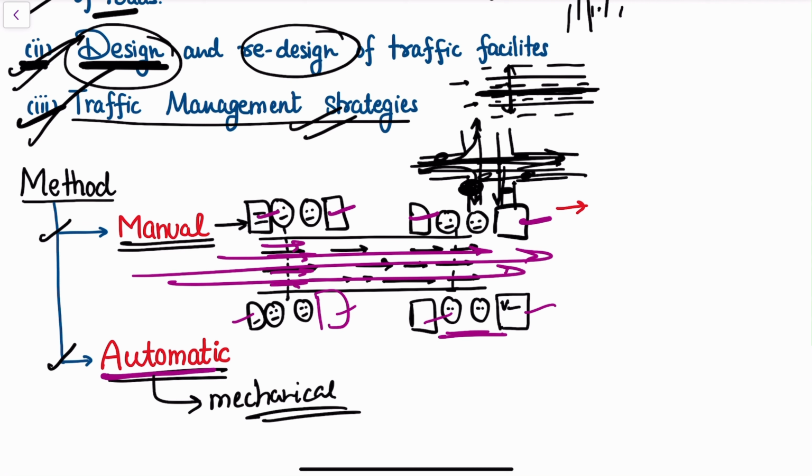While the manual method is a kind of flexible method. Suppose during the traffic study we want to add certain additional parameters. Let's say we want to bifurcate the traffic volume that is moving in the night and in the day. Likewise, we want to bifurcate the tandem vehicles from the tridem vehicles, right? So we can ask any one of the surveyors to please take care of this data, like please see if the truck that is passing is a tridem or a tandem, right? So the surveyor on the site can start recording the same thing, and can at any point of time give the results, right? So this is a certain amount of flexibility that is involved with manual methods.